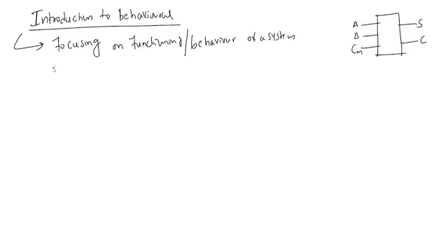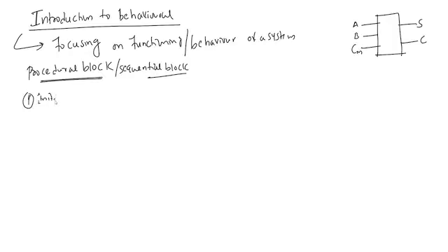And there are some procedural statements, some procedural blocks. This behavioral modeling you need to write between the procedural blocks. Those are nothing but what we can call sequential blocks also. So we need to write between the initial block and the always block. Whatever behavioral modeling is there, we need to write between the initial block and always block.